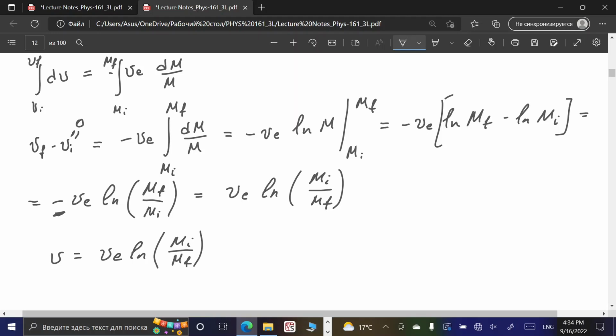Okay, that's the right answer actually. So what we need to do? We need to increase temperature of these gases which are ejected. So if we increase energy, the kinetic energy of these molecules, which are products of the burning of this, what actually happens there is oxidation of the fuel inside the rocket engine. So we want to produce per unit amount of burned fuel as much energy as possible, which results in increased temperature of this exhaust gas. If this temperature increased, the pressure inside the rocket engine increases, and obviously the velocity of exhaust gases will increase.